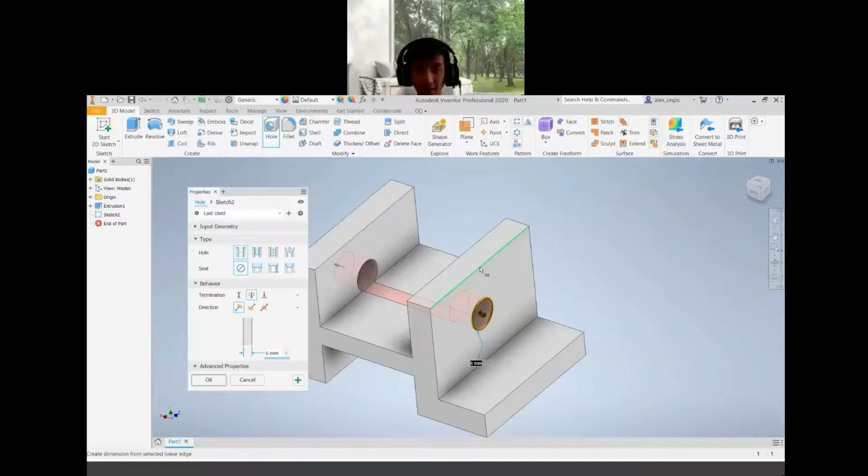So I click on this top line itself. Once you click, you see they will ask you to define the distance. You want this center point from this top line to be 5, so key in 5 here. Automatically, you see that the center point of that hole will shift up by that distance. This is only the first line.